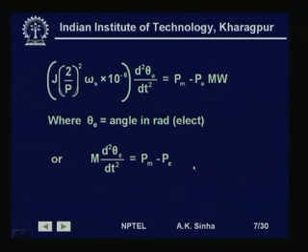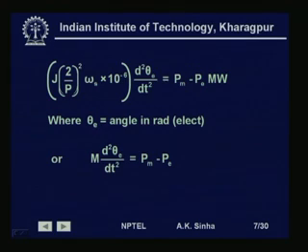Now, what we normally do is, because this theta e will keep changing with time, that is, with every one cycle of electrical rotation, theta e changes by 360 degrees electrical, and therefore it will keep on changing with time. So, instead of working with this theta e, which is with reference to a stationary reference frame, we work normally with a rotating reference frame, which is rotating at synchronous speed.